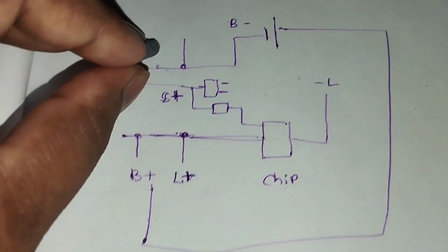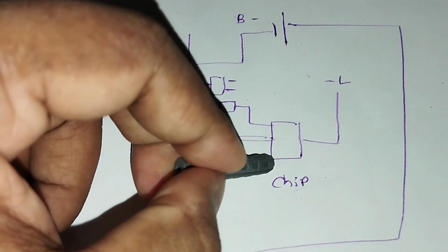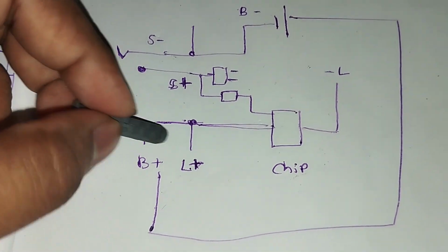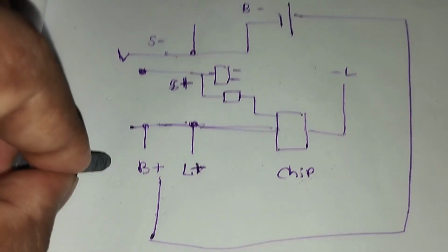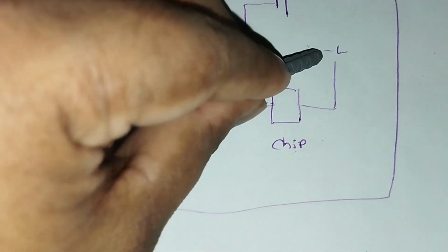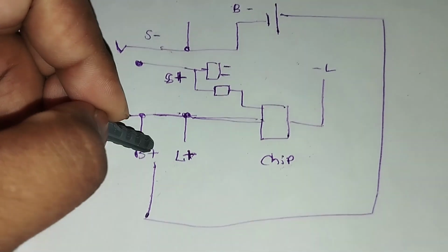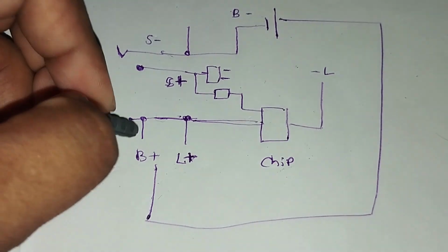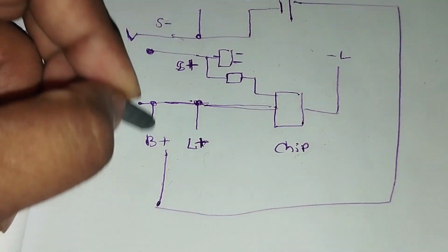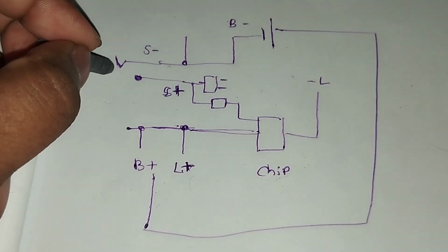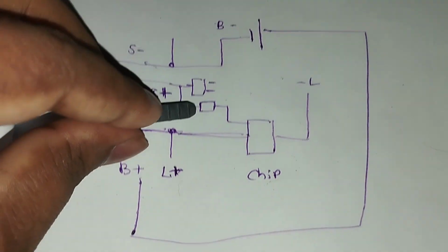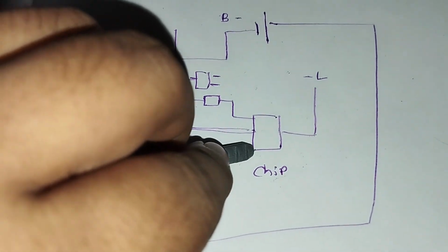So maybe there is some base of an NPN transistor. That could be the base of an NPN transistor. Then triggering that is very easy, without even needing a microcontroller inside this mystery chip. So the light switching is done by this chip, because the light is provided directly from the battery. The chip can even do battery monitoring, because the battery and the chip are connected. I hope this negative is also connected to the chip somewhere.